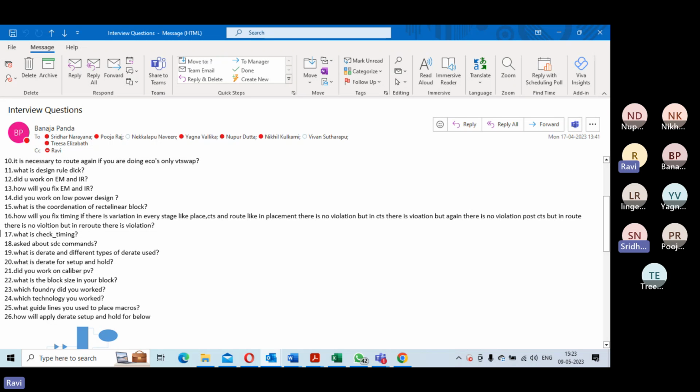So the fix is downsize the driver, increase the width of the metal, or reduce the fan out, split the net. These are all solutions to it. Okay. Don't talk shielding, etc. They have nothing to do with it. Okay. This is not a crosstalk.